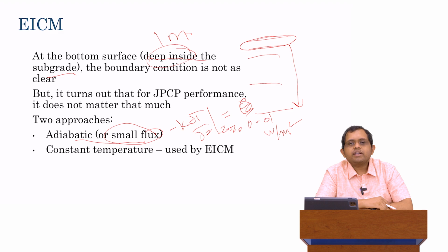So that's an additional assumption. Either we say that very deep into the pavement there is no heat exchange, or there is a very, very small heat exchange very deep into the pavement. So that's one assumption. That's an adiabatic assumption.